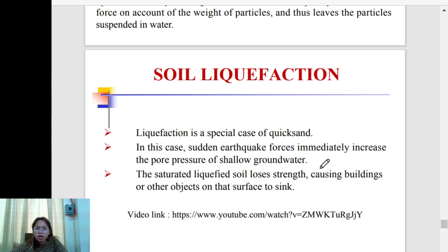So actually, it triggers liquefaction when there is an earthquake, especially if the soil is more silty or more fine sandy, more liquefaction na siya. So you can observe, I think in Japan, in the Tohoku earthquake, there are areas where the soil liquefied. It is dangerous especially for the foundation on the soil. The structure will really fail.